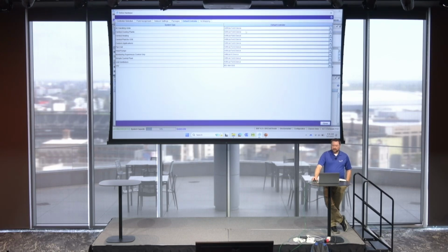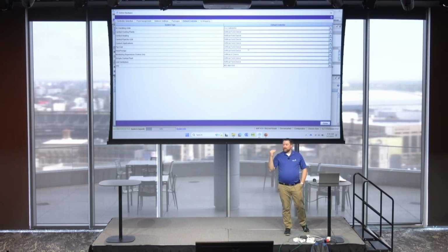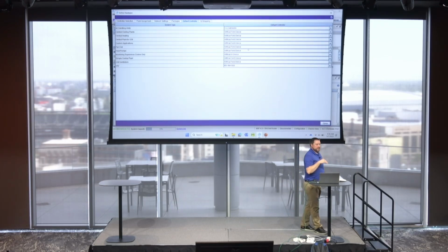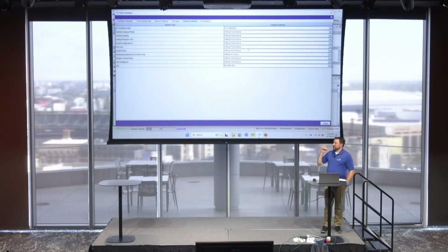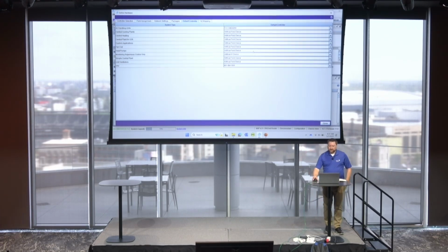And you'll see there's the different system types here: air handling units, central cooling plants, custom apps, et cetera. So here I can take this air handling unit and say, okay, whenever I do an air handling unit, I'm using a CGM 4060. Probably not the case, but it's the first controller I saw there, right? So instead of having to define the controller each time, now you just spin up air handler, it has your predefined selections, has the predefined controller. Those steps are taken out of the equation for you.